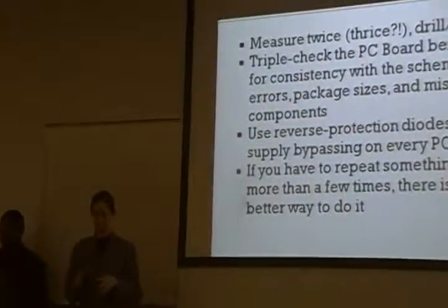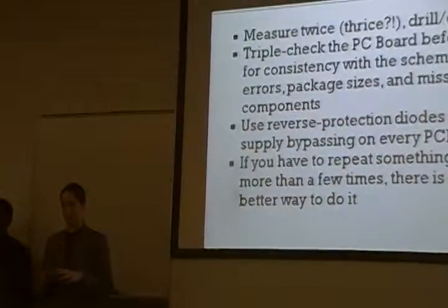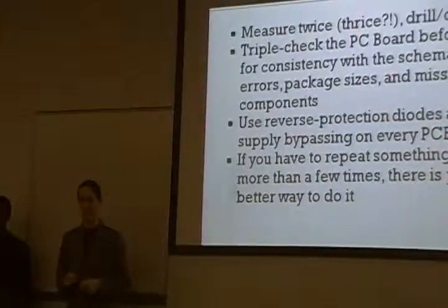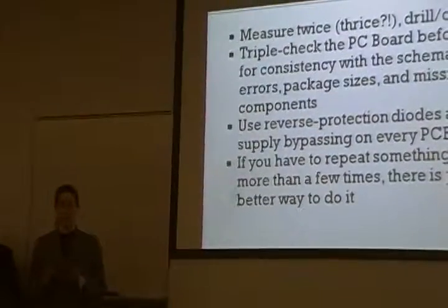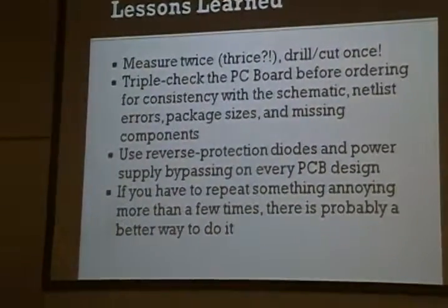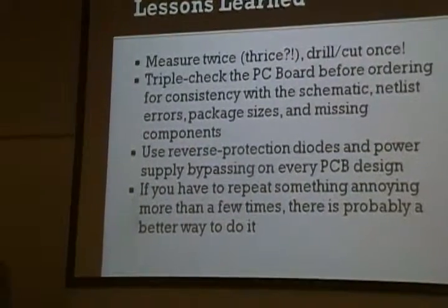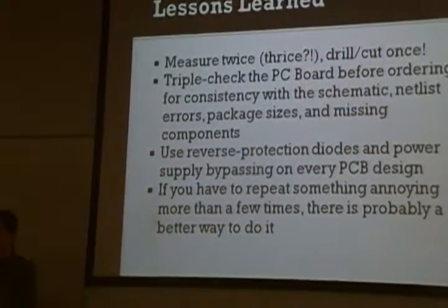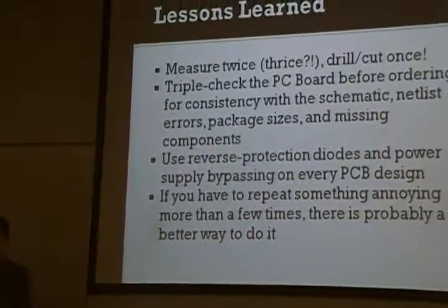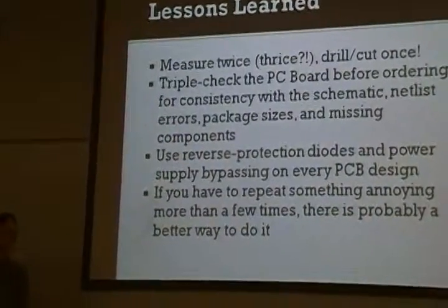Then, before you send out the PCB to be built by a company, you want to make sure that the PC board is correct. You don't want to do any sort of alterations once it comes back from there. It's not easy to do, and it's a lot of extra time you don't need to be wasting on it. Also, protect your board against any problems you might have with voltage concerns or current draws that may happen if an unknown component that you're working with might accidentally break or suddenly explodes on you. You want to make sure that the rest of the PC board isn't compromised if something like that happens.